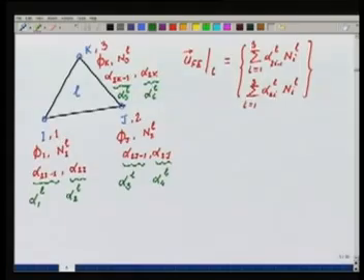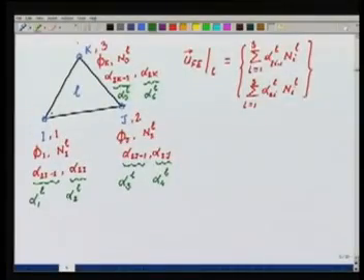Again, if you see, we have done a counterclockwise enumeration of the degrees of freedom. That is, we went from here to here to here and not from here to here to here. This is our choice. It's not that I have to make this node 1, I could have made this one 1, but it's the naming convention that we choose at the element level. The bottom line is it should be counterclockwise. The nodes should be numbered in a counterclockwise manner.